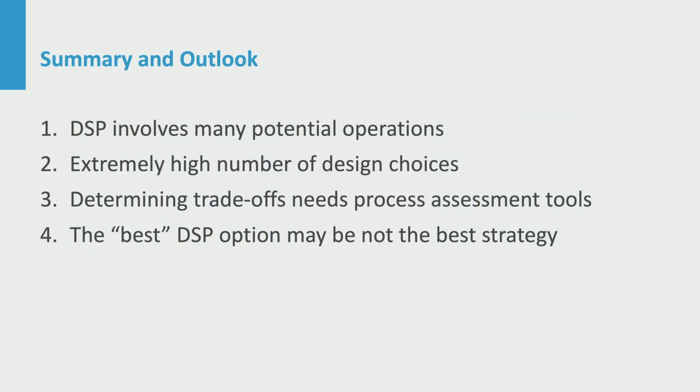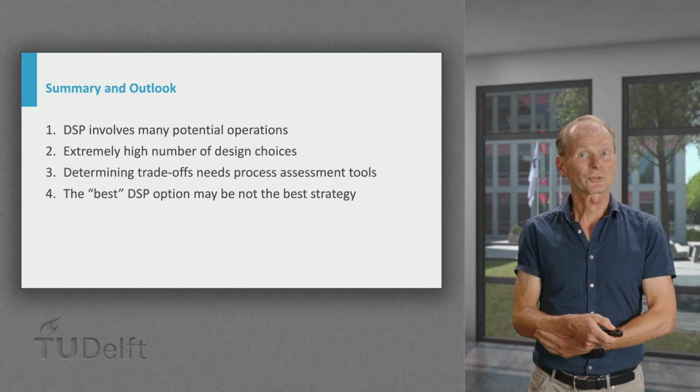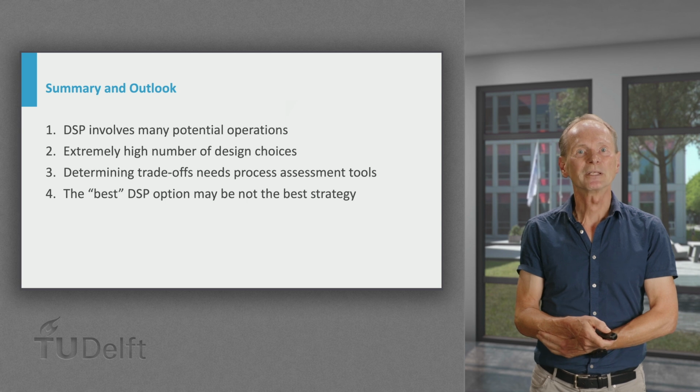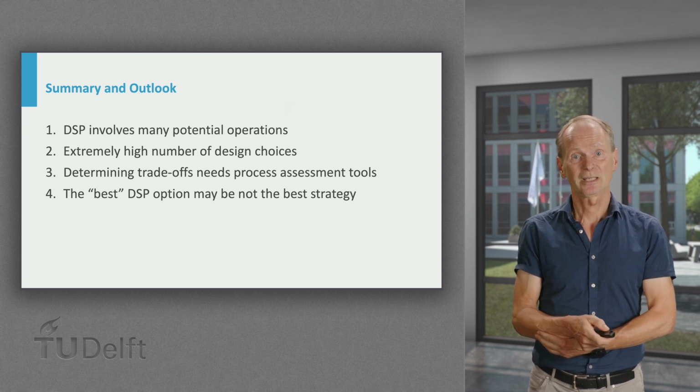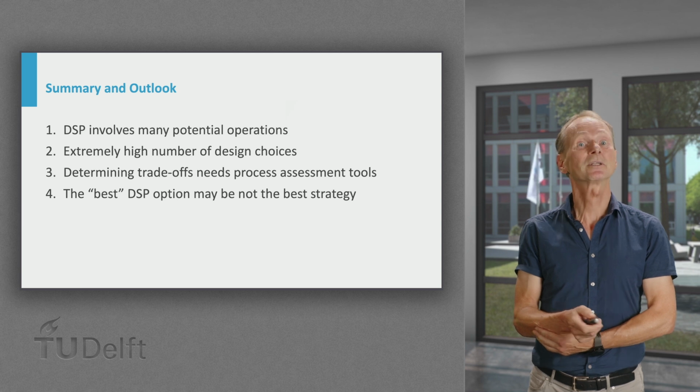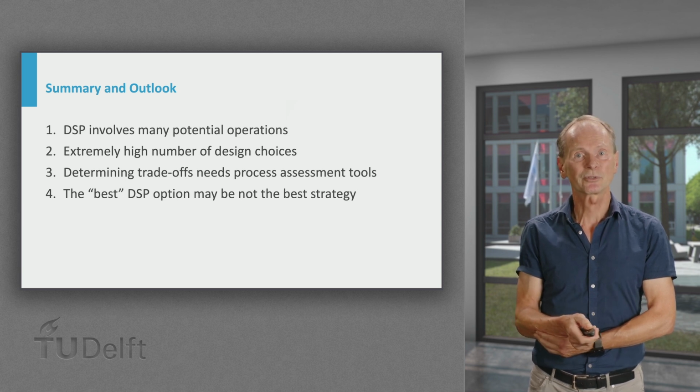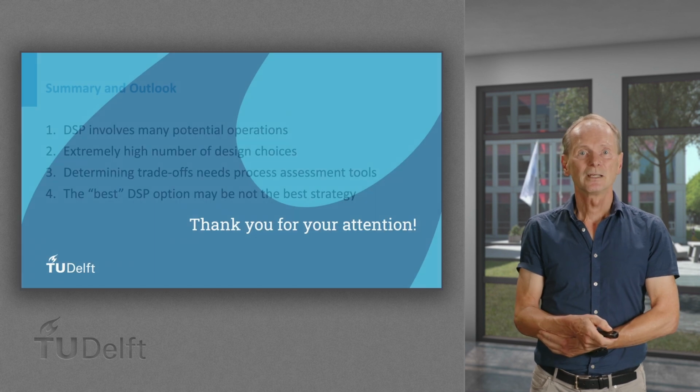From the simplified PDO case, we have learned that DSP is challenging. It involves a lot of different operations. Each of those has numerous design options. Typically, alternatives would need to be compared on recovery yield, energy use, equipment requirements, etc. This requires process assessment, such as elaborated in the later week of this MOOC, and iterations. However, considering the number of DSP options, it may be impossible to find the best option. A better strategy is to develop a good enough option in which DSP is not the bottleneck of the overall process. This was DSP in a nutshell.